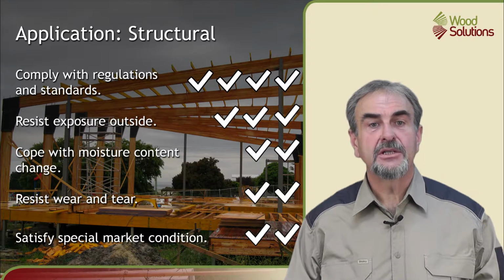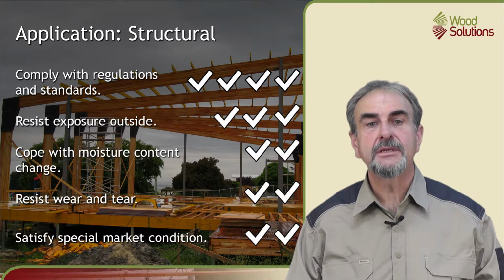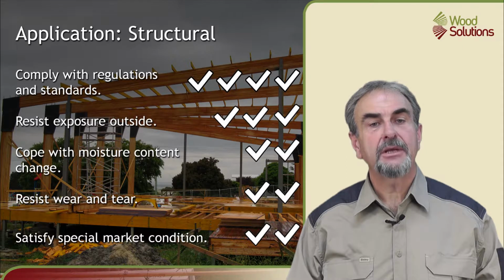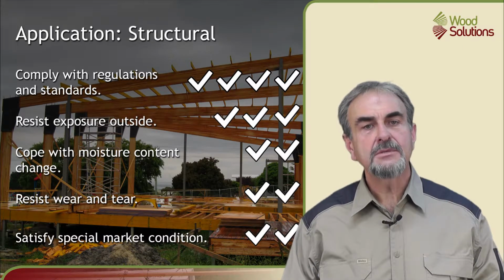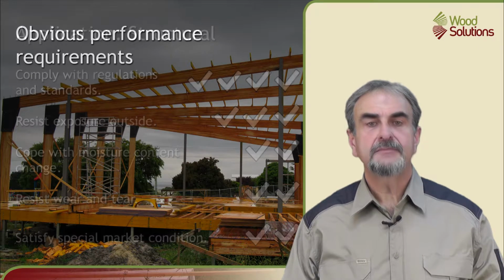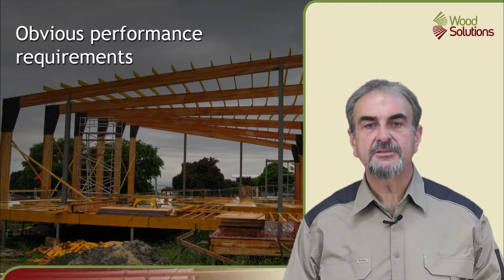Structural applications include uses such as timber stud framing, columns and beams in multi-storey buildings, wood elements supporting major roof structures, poles, piles and a range of other uses. Numerous timber products are used in structural applications, including timber rounds, sawn boards, plywood, laminated veneer lumber, glulam, nail plate trusses and others. Having determined that this is a structural application, some key performance requirements are clear while others have to be confirmed through further questions.